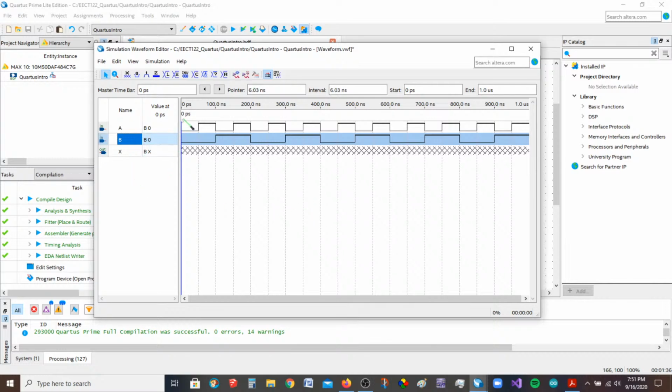So here's how that works. If we look at this as a graph of amplitude versus time horizontally, if I drag my cursor to any point in time, the question we're asking is, like this very first point in time here, if I put that A at that point and that B at that point through that AND gate, what happens to the output? Well, we know that an AND gate has to have a high before the output is high. So I'm predicting that this very first section right here is going to be low. The next section over, we have a 0, 1, which through an AND gate is still a low. So low, low is what I expect.